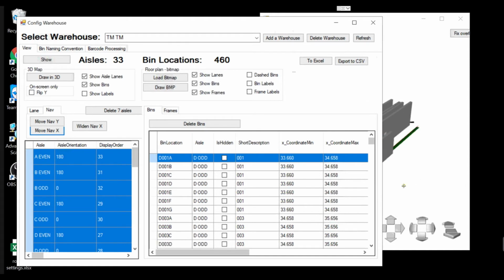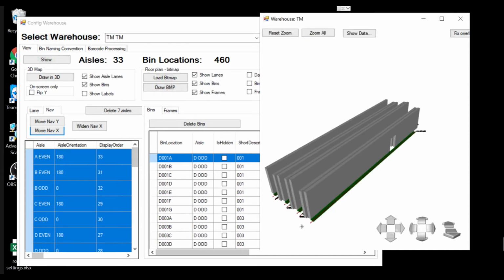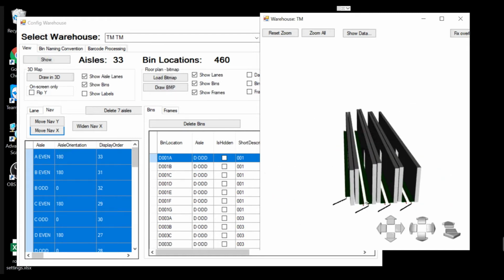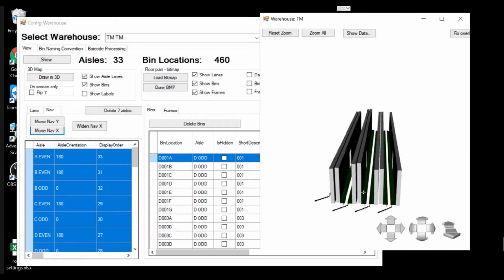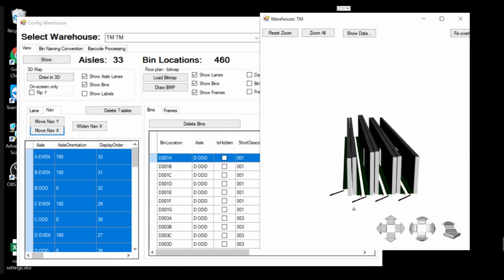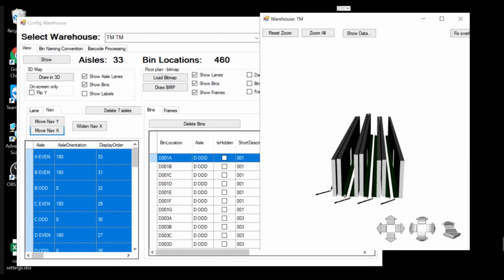and we have now aligned the coordinate system. So the robot will come here, navigate to the end of that aisle, and then it will turn around and navigate down there. So those are navigation points, seem to be okay. The lanes are a little bit narrow. You can see there's a section in the middle where if the robot went into that area, it wouldn't know where it was. It would think it's in a no man's land, and the aisle would be blank.